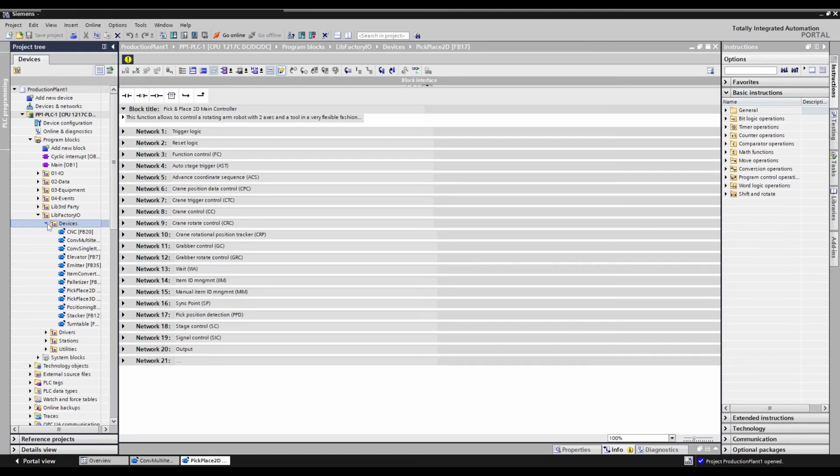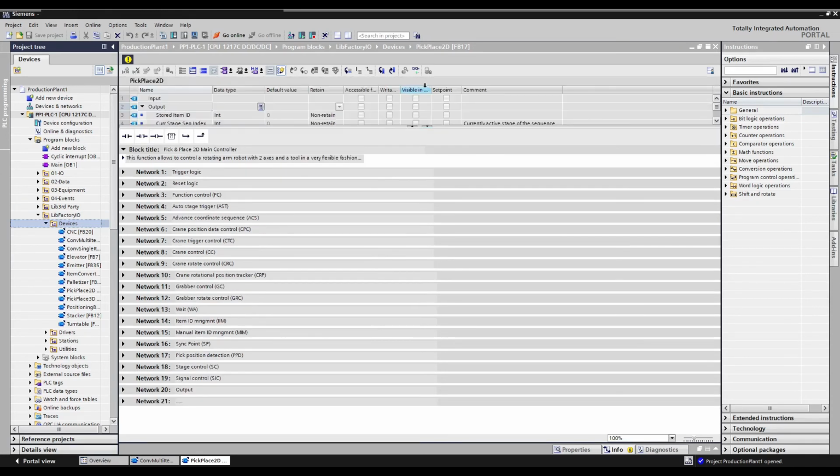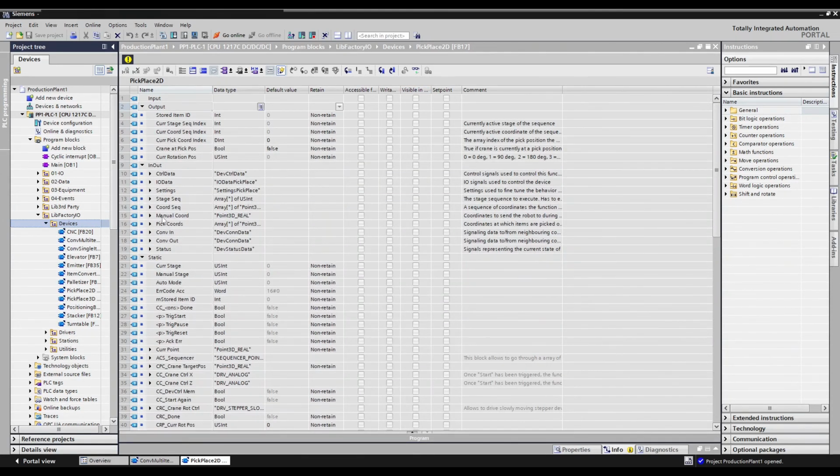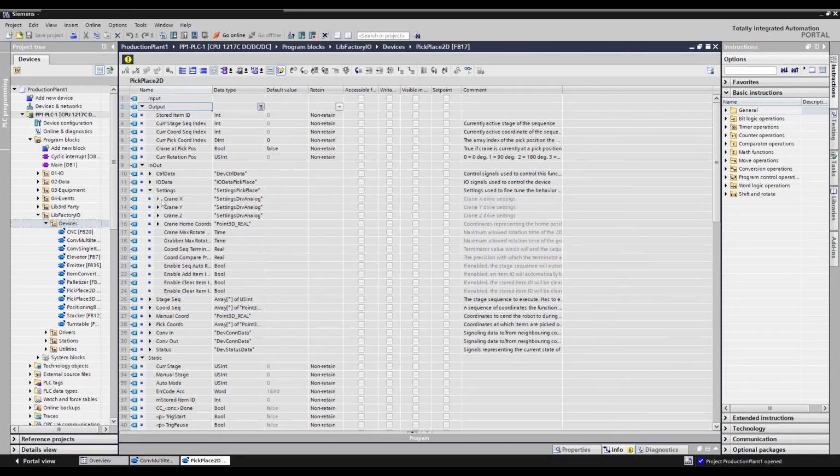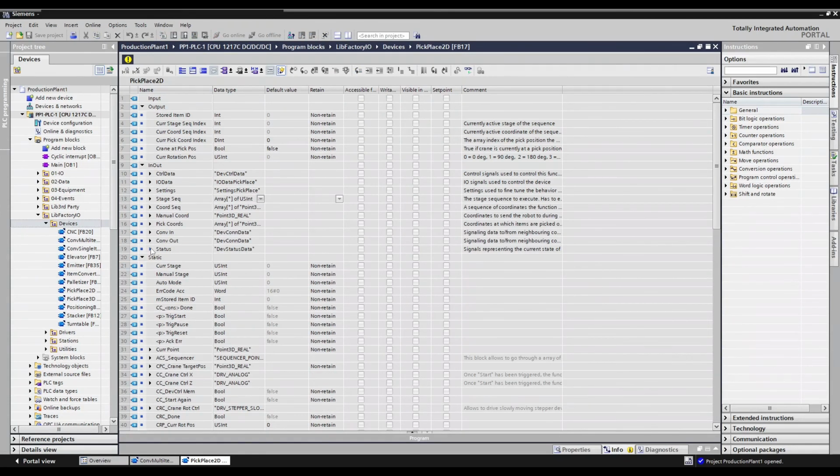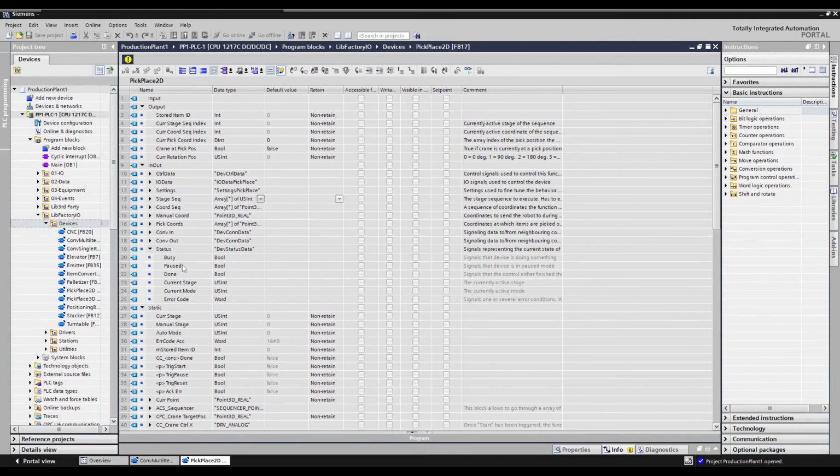But to encourage using a proper way of accessing data, I defined the settings and status UDTs, where the settings are basically the setters, and the status UDT we can think of as a getter, and these are responsible for providing data that we should be able to access from the outside.